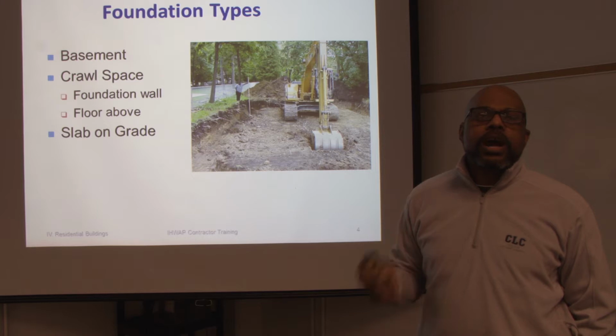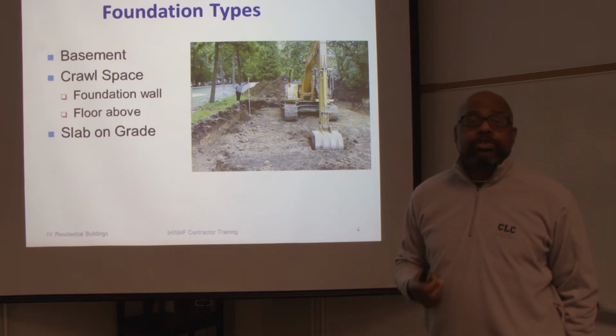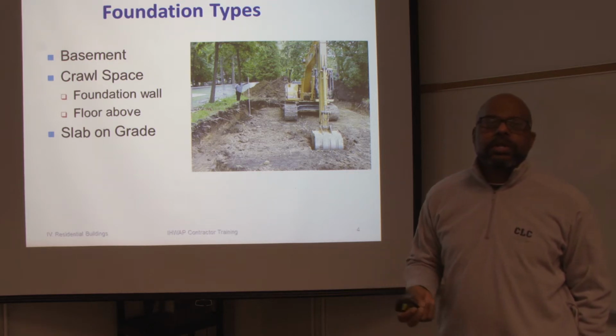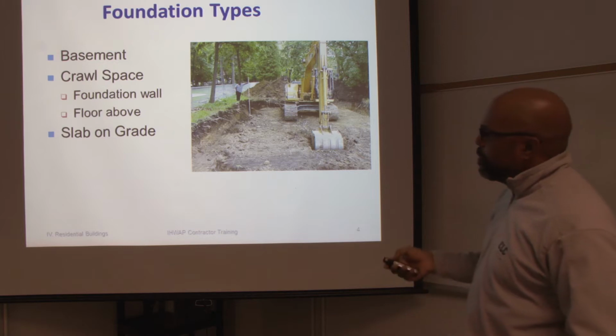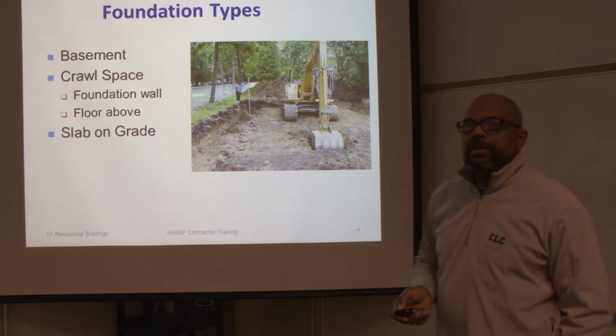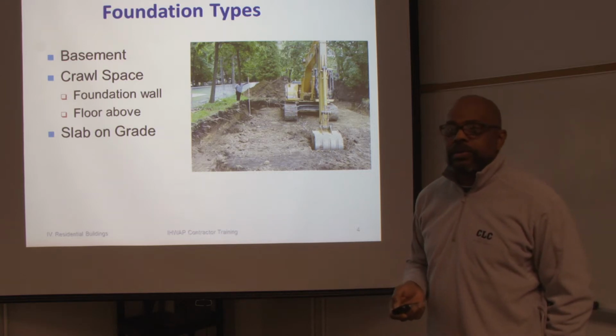If it is a concrete slab, the slab has to be kept at a certain temperature, so they would run ductwork inside this concrete slab to add heat to it. Without that, the floors get very cold. As a matter of fact, it could condensate or even frost based on the outdoor temperature.